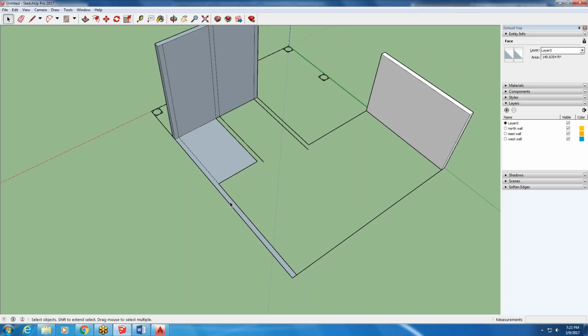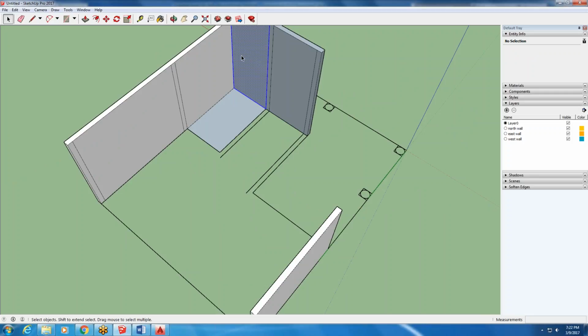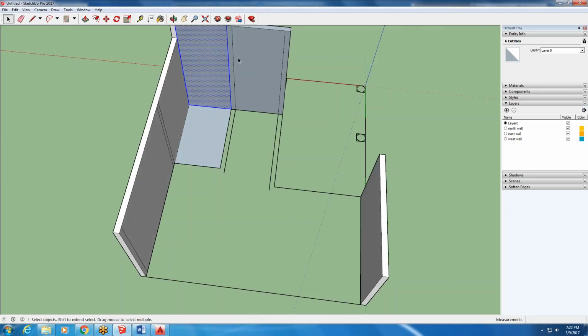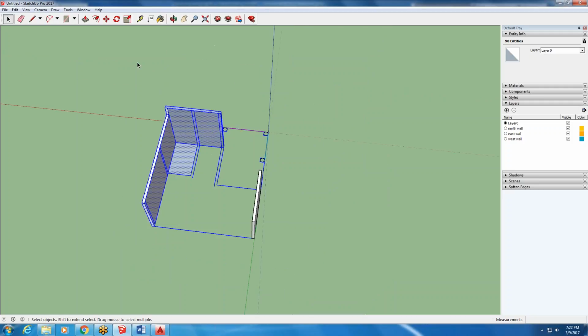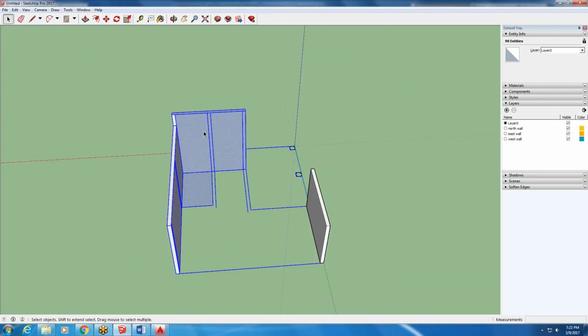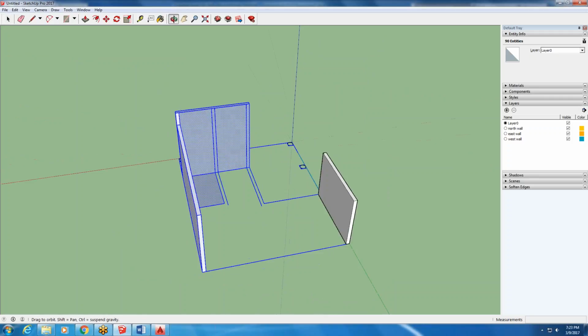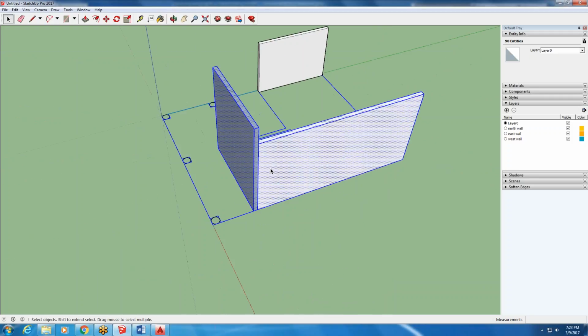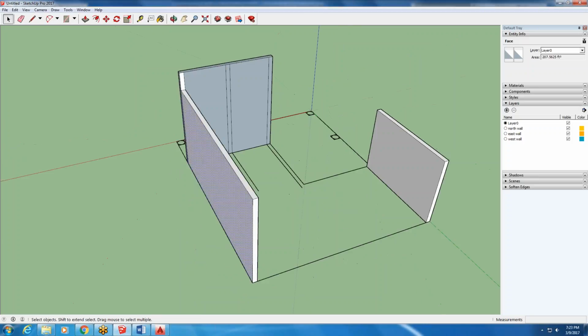So this is a nice clean rectangle. It might let you triple click it, but then you push pull it up some or whatever, and then you go to triple click, and it's letting you. There's going to be a point where you get too deep, and then you can't select just one thing. You can't select just this group anymore. It's all one solid thing, and it's become its own entity. We have to keep it separate or the geometry starts running together, and it gets really messy.